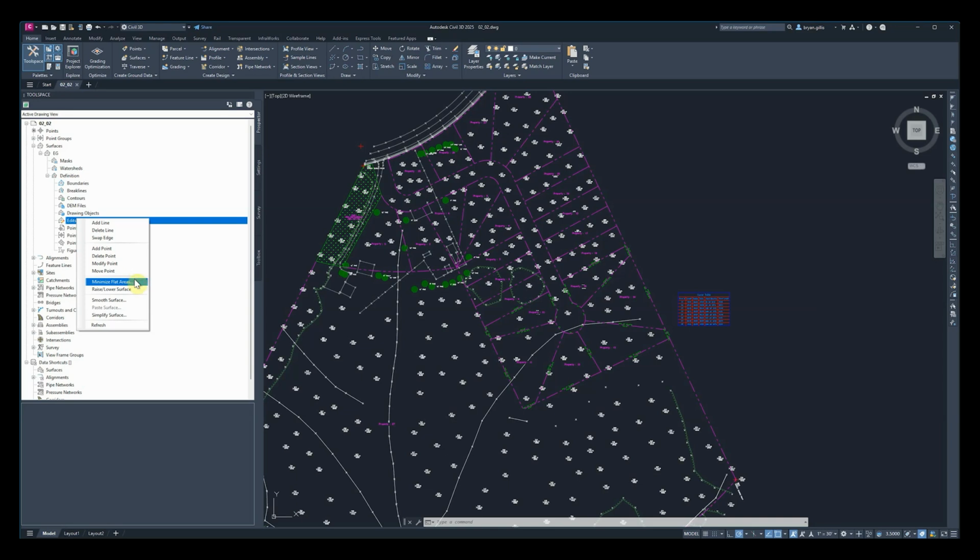That creates an unrealistic flat area that should not actually be there. So it's an inaccuracy. This tool would automatically identify those flat areas and break away from whatever its standard definition was for creating that triangle, and utilize points that are not along the same contour to try to create a more realistic representation of that surface.